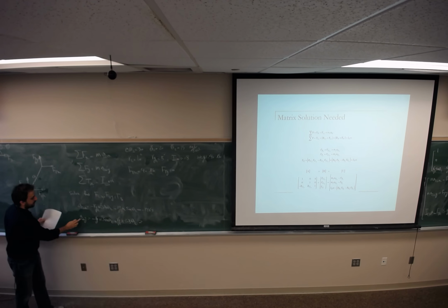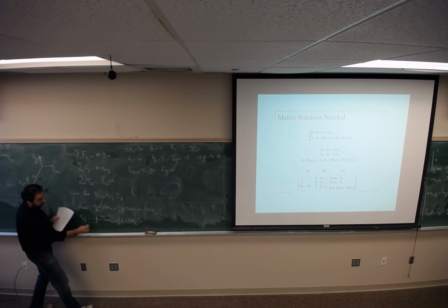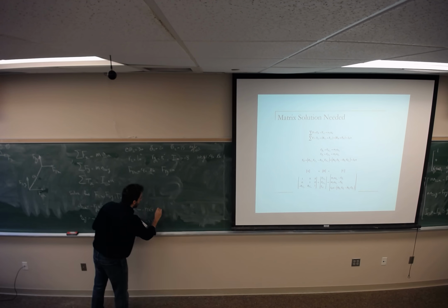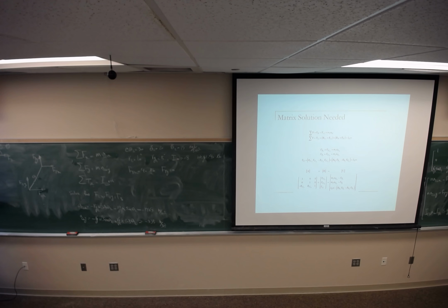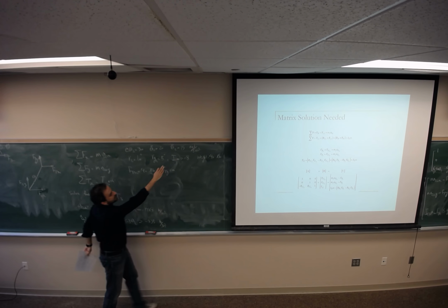For the center of gravity, the acceleration of the point in the y direction, you will find negative 935 inch per second square. It's the acceleration of a point, so the unit should be inch per second square. If it's angular acceleration, it's going to be radian per second square.